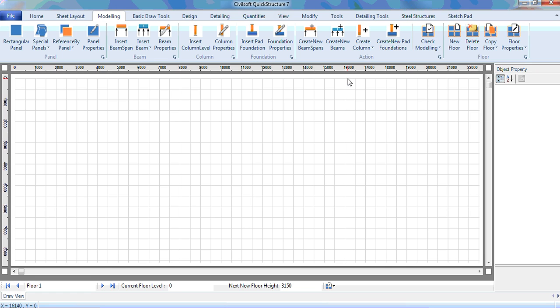Before I create my coordinates or the grid lines, first of all you need to know that the grid is at 500 interval. That is the regular grid, but your own grid must not be at the regular intervals. They can actually be anywhere. I will show you that in a moment. Secondly, you need to understand that my 0 point starts here and then it increases.